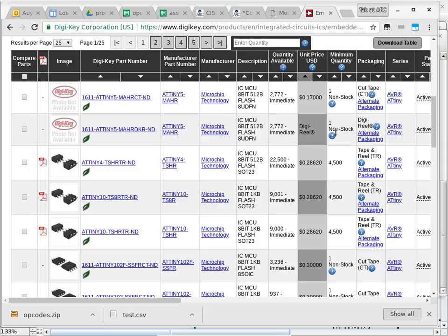But think about the application. These things are easy to work with because it doesn't need any external parts. You give it a zero. You give it the voltage, from 1.8 to 5.5 volts. It has the internal oscillator. It just runs. So minimally, what you need to run these things is really just a battery and the part.